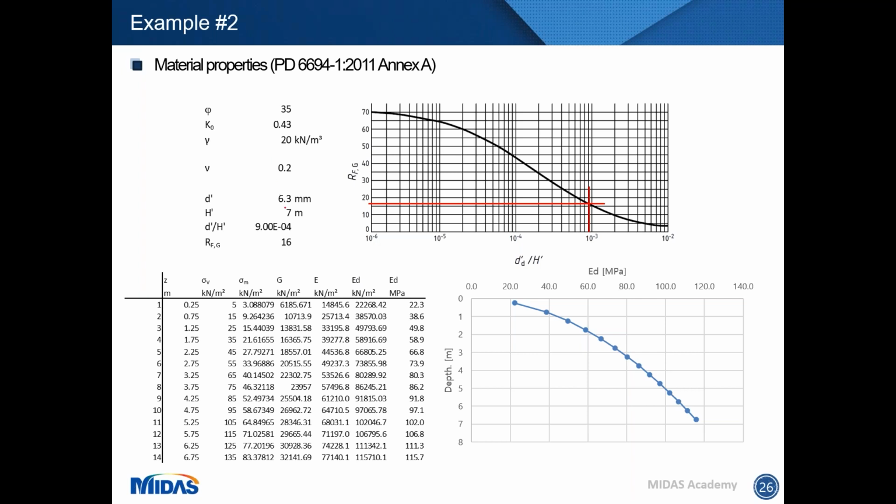So what are the values for our soil properties? Well, we know our free expansion initially. For the deck, we're going to assume that it's the free expansion of the deck without any restriction. From that, we are going to be able to calculate the D prime, that's the movement at half depth of the abutment wall. And with that, we are able to calculate the soil properties at different depths.